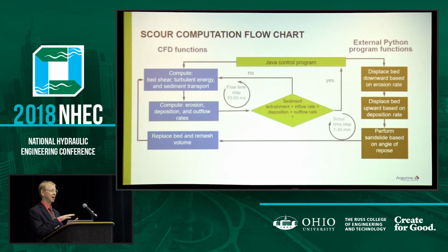And then what's going to happen is, as the scour holes form, the entrainment rate is dropping. It's this decay function that Cornell has talked about. So you've got a lower entrainment rate in most cases. Sometimes things change, so some spot may have more, and you have to wait until that change propagates downstream. Then that's a converged CFD state, and you go back over to the other side at that point.